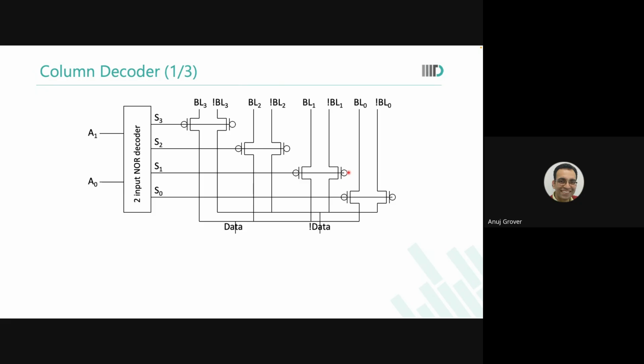speed came, because you don't need to discharge the bit line to lower than VDD by 2 to be able to sense whether to transfer 0 or 1. That job the sense amplifier will do. See, if you put the sense amplifier above it, then you can put that kind of MUX also. But if the sense amplifier is beneath it, you only need an analog MUX, a pass transistor type of MUX. You cannot have a digital MUX.